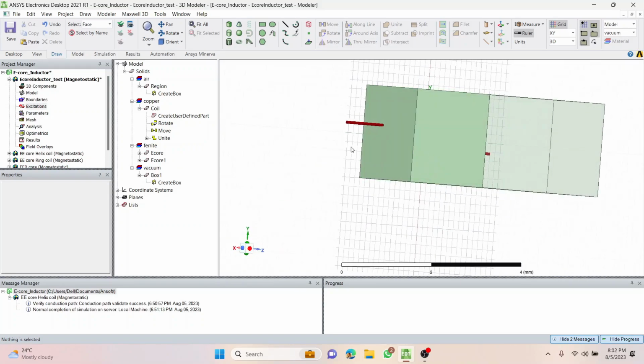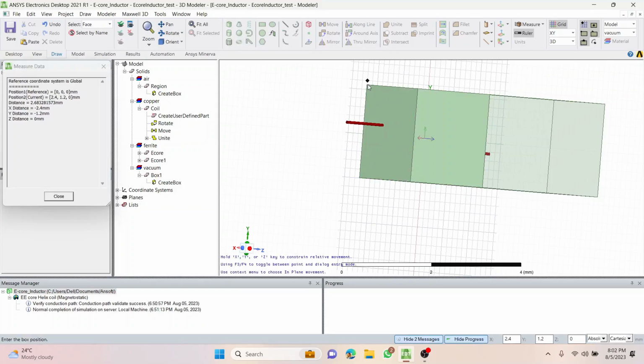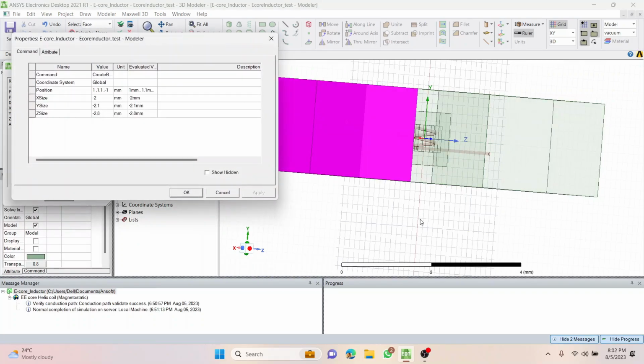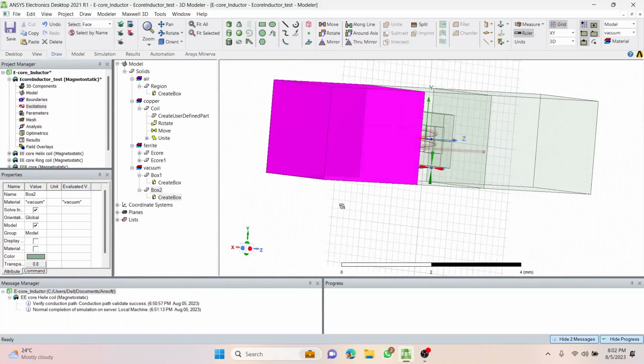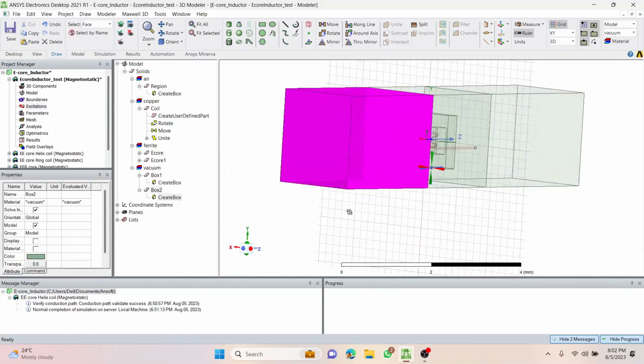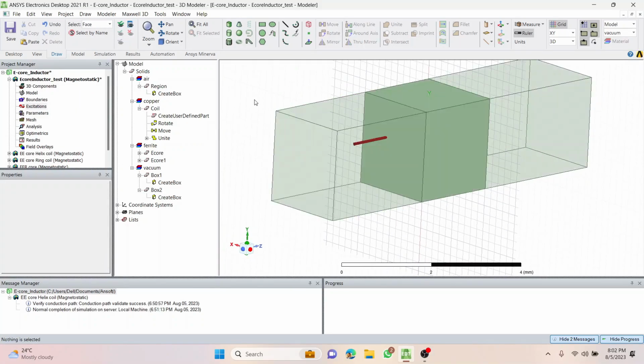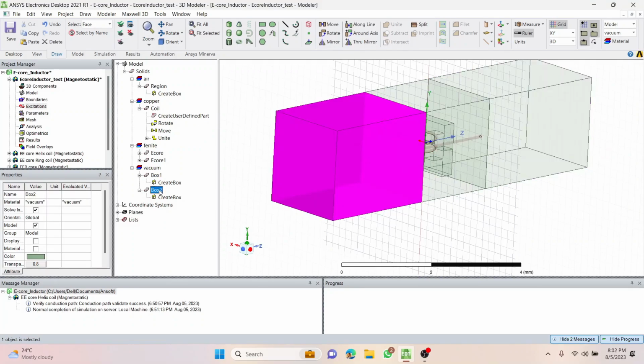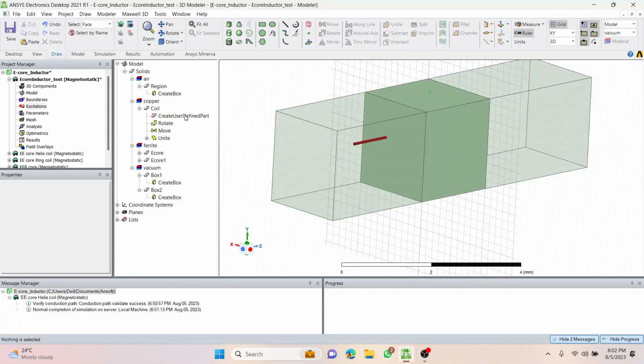Yeah. Similarly on the next direction, again same plane, so no worries. Provide the cuboid, draw the cuboid, bring the extension, oops, and it is covering it, right? Perfect. Now what we'll do is Boolean subtraction. So this is box 1 right over there, this is box 2, both of them are covering the extension.